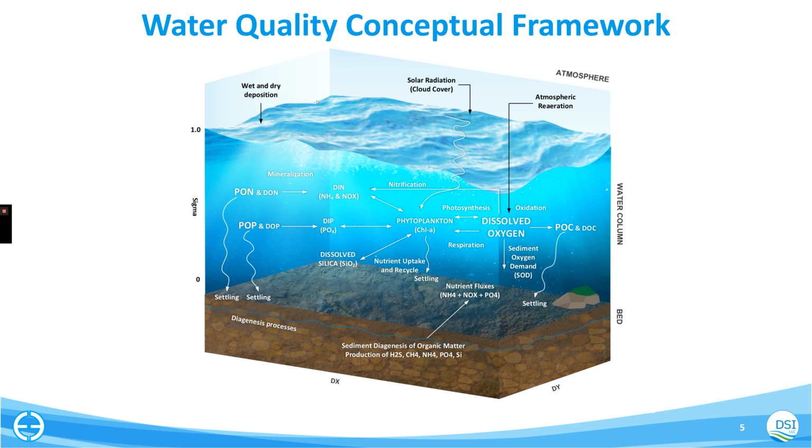So anyways, it's a very coupled model between the hydrodynamics and the water quality, which is really nice. But of course, that means you pretty much have to run them simultaneously. You can't decouple them if you want to actually link the feedback from the water quality back into the hydrodynamics.